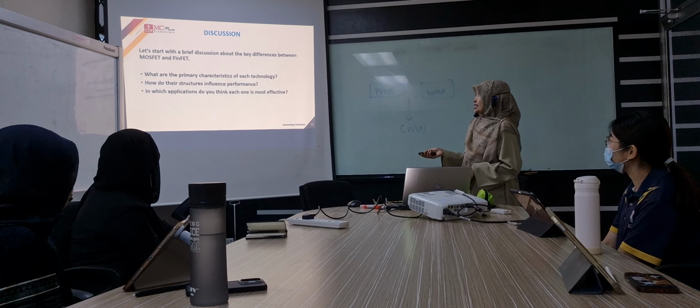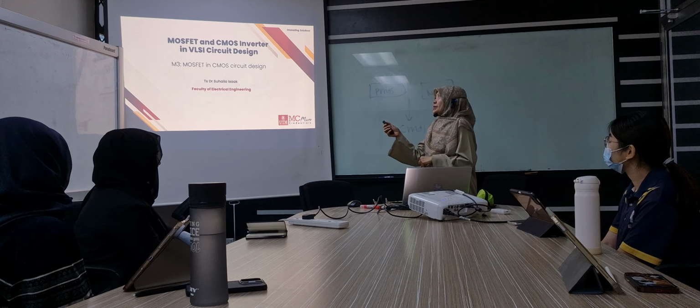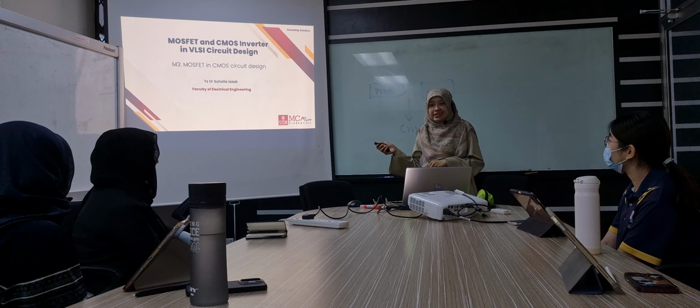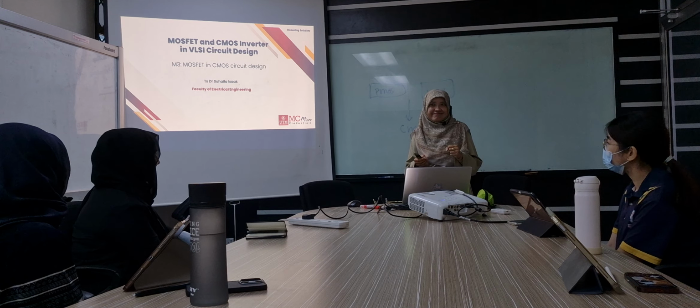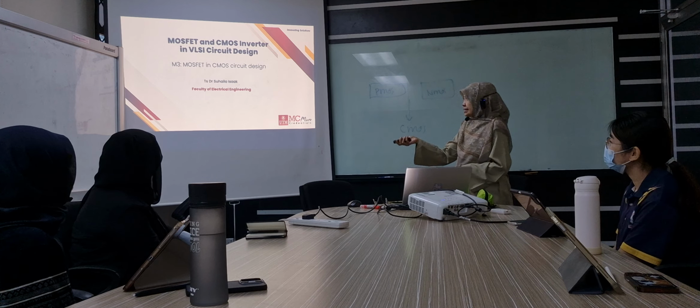Okay, next, let's look at what we have for the next part. We will cover MOSFET in CMOS circuit design. In this training you will learn how to design, how to come up with linear region, saturation region, and also cutoff region. In the saturation region, we have two parts: one is pinch off saturation and the other is velocity saturation, when the channel length is shrinking.